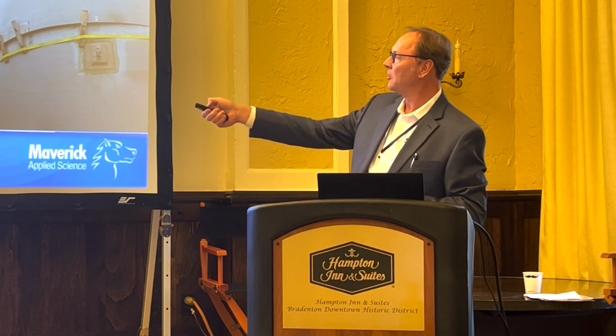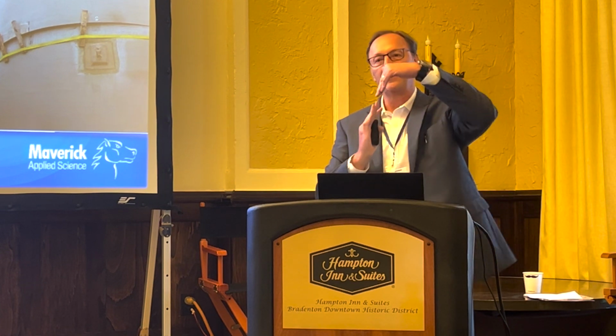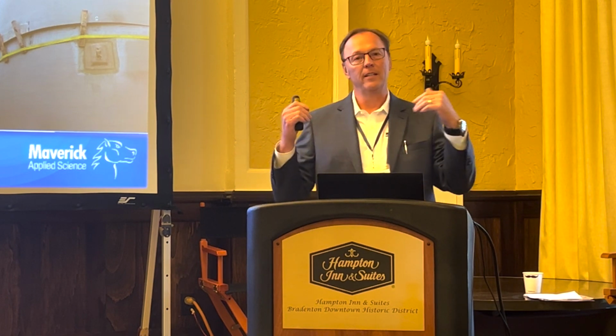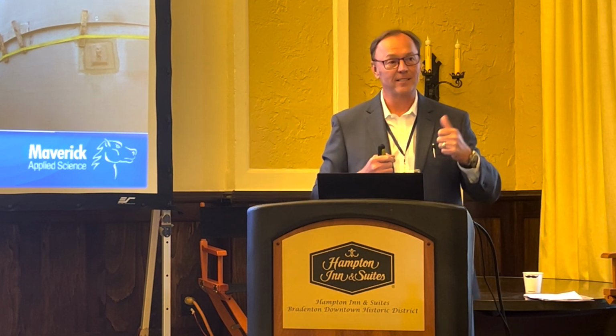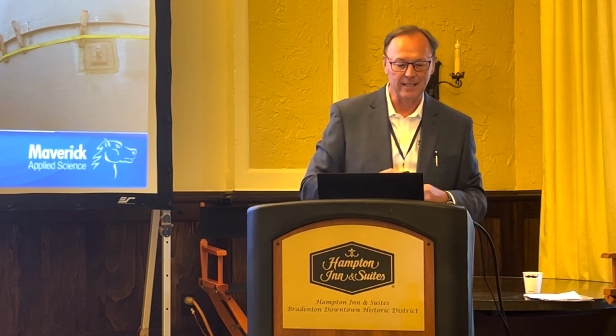Tanks are designed to be vertically loaded and things in plane. So as soon as you have that offset, you're introducing a bending moment into that joint, and you say, okay, let's put another 1/2 inch on there, and that'll make it strong enough. Well, it's rare that you're going to do an FEA or something like that and say that's okay. You're going to say, all right, we'll buy that. So that's one of the compromises that can happen.